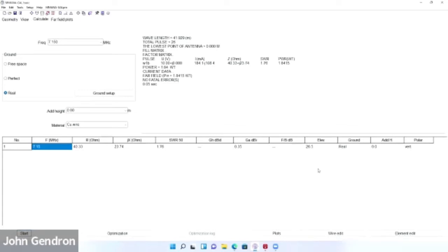So it's a little bit different, but if you go back and watch that first primer I did on antennas that I did the presentation on and I put up on YouTube, it'll go deeper into those imaginary and real numbers. Okay, the real number we want close to 50. We want that reactance as close to 0 as we can get it.